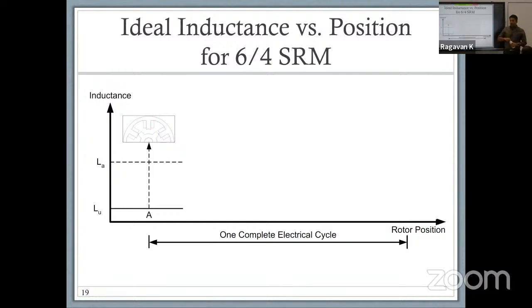Sorry. It is relative flux, you're right. Exactly. It's not like an electric circuit. In an electric circuit, if the circuit is open, nothing's going to flow. But in this specific scenario, your rotor is still within range. If it was completely far off, if the distance was high enough, then this number would have been much lower. This, by the way, is not a number, it's just an illustration. So the goal for us, even as we design an SRM, and we will talk about it later, is to lower this number as much as possible and increase this number as much as possible.